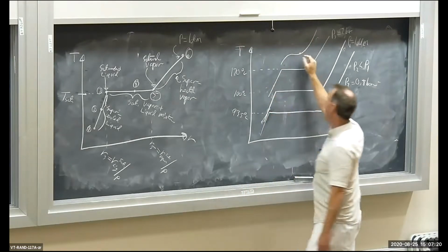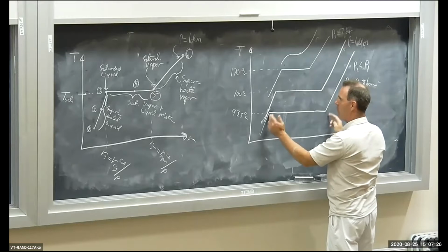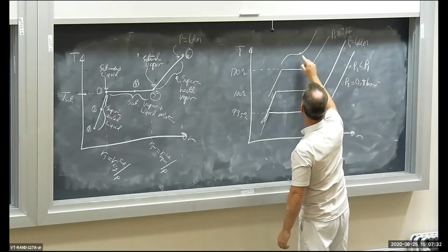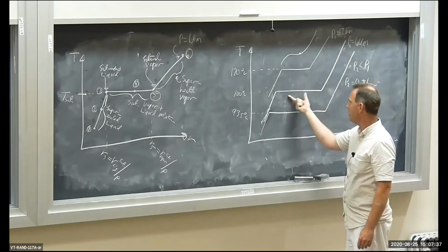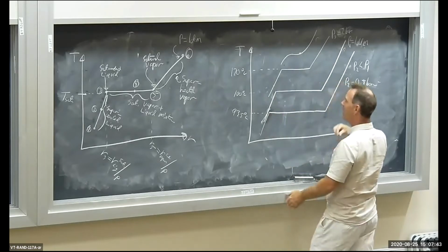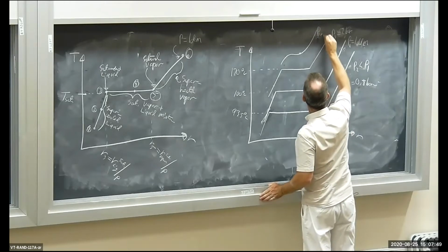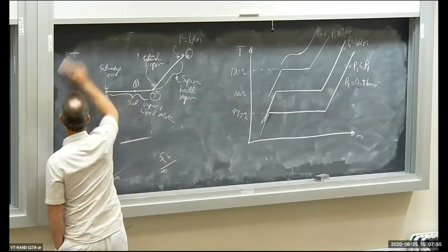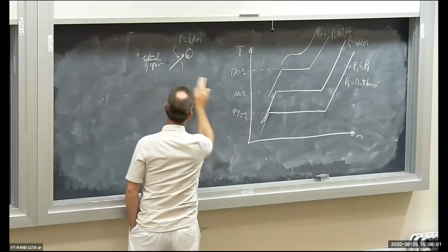That one does not have a flat mixture region. See, in the flat region where the boiling is isothermal, you've got a mixture of liquid and vapor. This one doesn't have a flat region. On that last isobar, the boiling actually disappears, the gap between the saturated liquid and the saturated vapor specific volume is gone. This pressure is called P crit, the critical pressure.